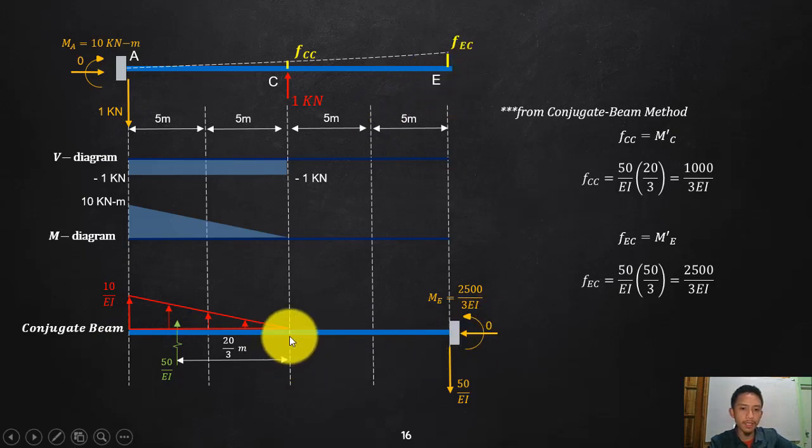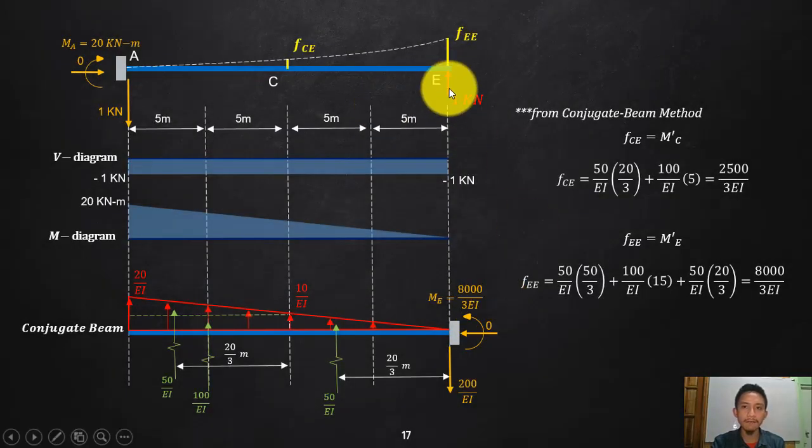Okay, get the moment again at point C, that is the small deflection at point C. So get this one, that is 50 over EI, moment arm 20 over 3, moment is clockwise, so that is positive deflection, which is true. And then the moment at this point, plus 10 to that 20 over 3 will be 50 over 3, clockwise still, so that will be 25 over 3 EI. Okay, now let's apply your redundant at E, which again is a unit load or unit force.